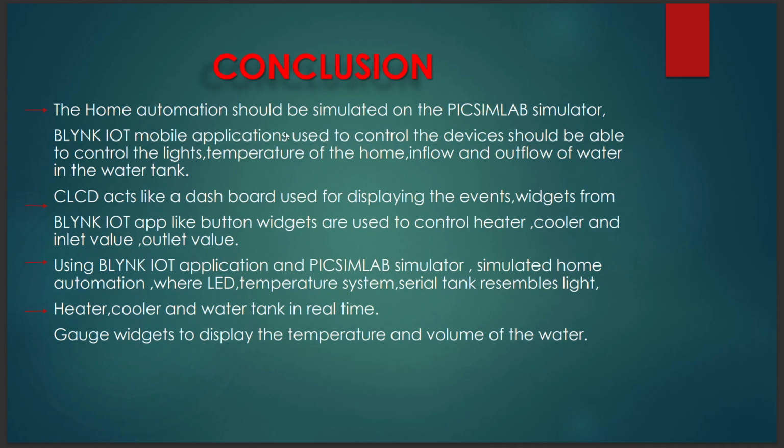The home automation should be simulated on the PicSimLab simulator. Blynk IoT mobile applications used to control the devices should be able to control the lights, temperatures of the home, inflow and outflow of water in the water tank. CLCD acts like a dashboard used for displaying the events. Widgets from the Blynk IoT app like button widgets are used to control heater, cooler and inlet valve, outlet valve. Using the Blynk IoT application and PicSimLab simulator, we simulated home automation where an LED, temperature system and serial tank resemble light, heater, cooler and water tank in real time. Gauge widgets display the temperature and volume of the water.